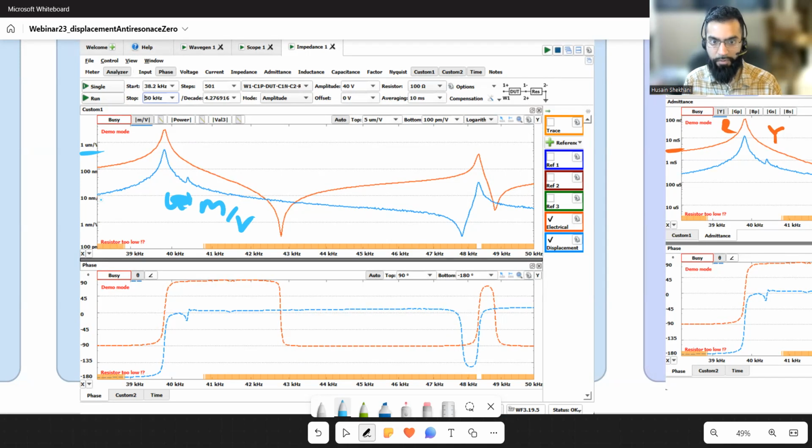There's a minimum where the phase changes back at this mechanical anti-resonance. So the mechanical anti-resonance affects the phase, and then it comes back up. It goes back up through this resonant point here. This is the resonant point, our traditional resonance, and then it goes flat again. And we know this should probably be 180 degrees, so you probably have to shift that if you want it to be real or actual, what it is.